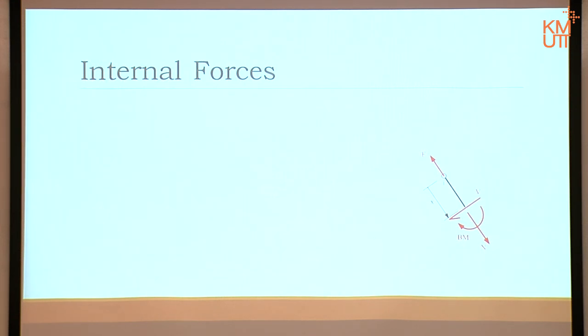Let's get rid of those. Look at that one. What happens if I combine the forces in the V direction, in that direction? That F doesn't count, that N doesn't count. To be in equilibrium, it only means that the shear has to be 0. Don't forget, this is not a specific case. This is a general case, meaning you can pull any member, the same proof will exist. What it means is that in pin joint truss members there is no shear. We don't have to calculate shear.